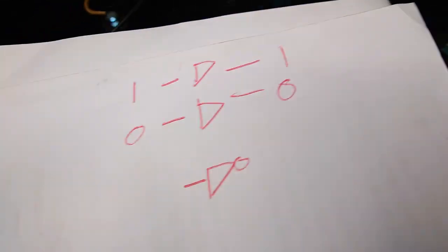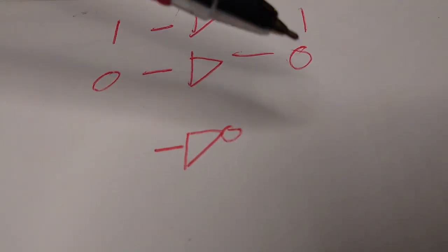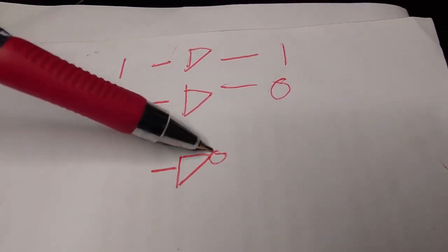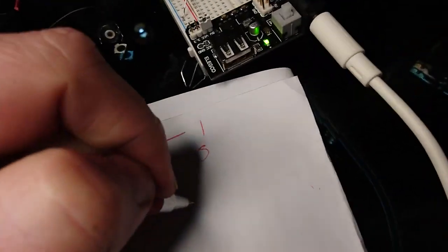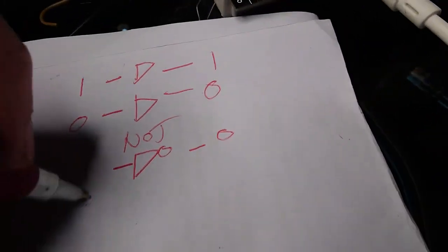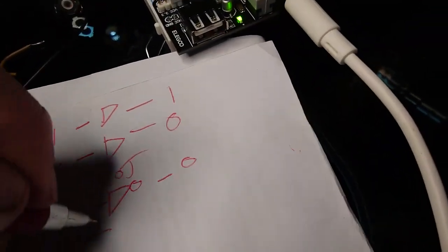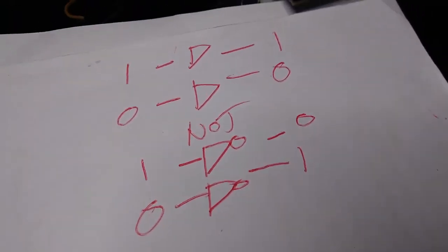Anyway, what we want to do is instead make a NOT gate. That looks just like the symbol for a buffer, but it's got this little 0, or little O, at the front. And this generally means negate something inside our circuitry. So if I put in a 1, I'm expecting out a 0. Just to be clear, this is for a NOT. Whereas if I put in a 0, I'm expecting out a 1. See how we're getting out the opposite of what we put in.